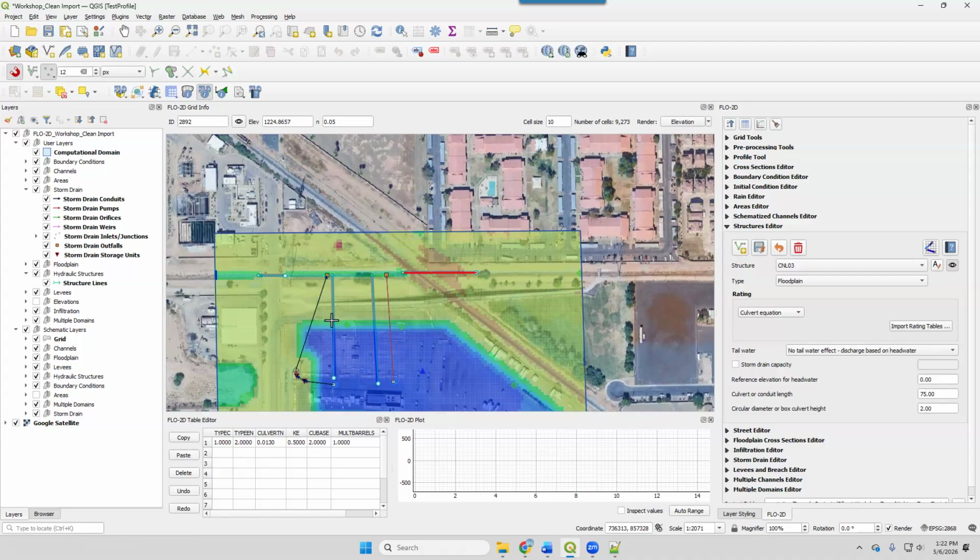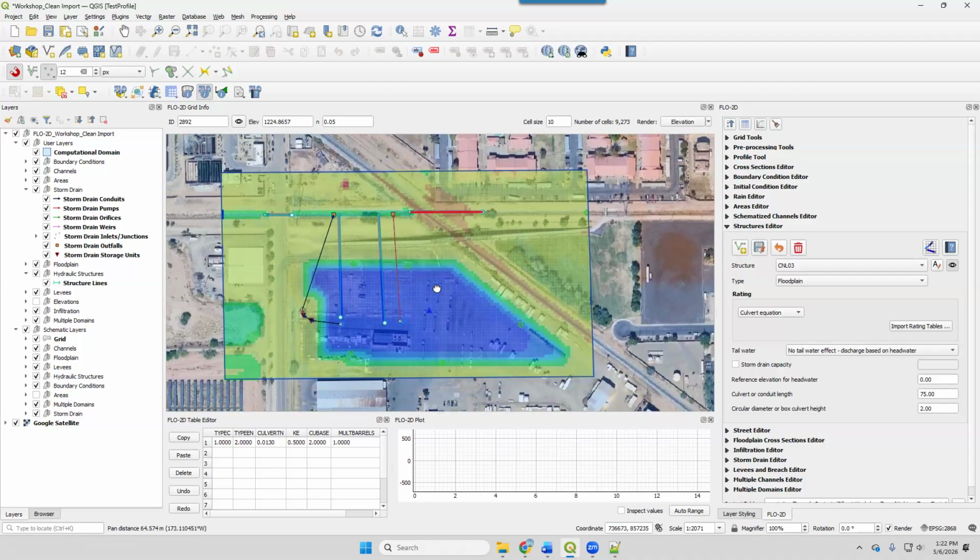flow through the system. And then the pumps are going to, as this basin fills from these inlet nodes, as the basin fills, the pumps are going to turn on, and then in addition to that 6 CFS, we're going to start to see flow through these pumps and then down to the outfall. I'm sorry, to the outflow condition, the boundary condition.